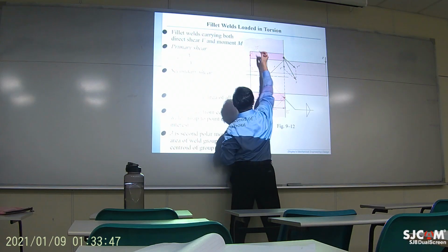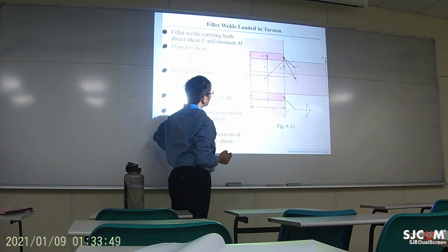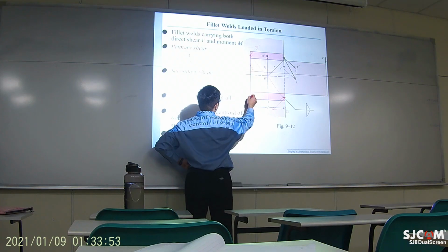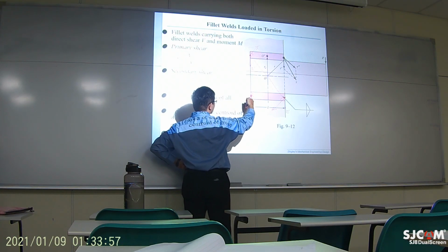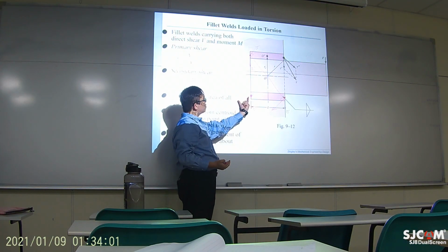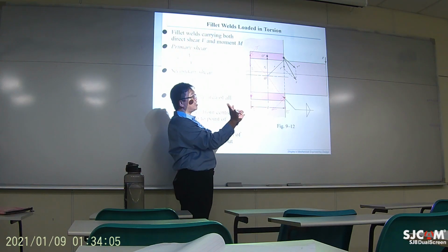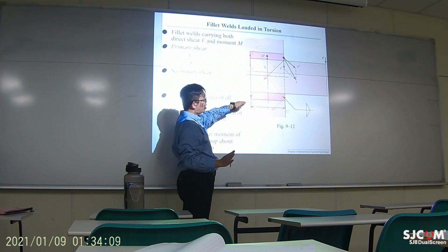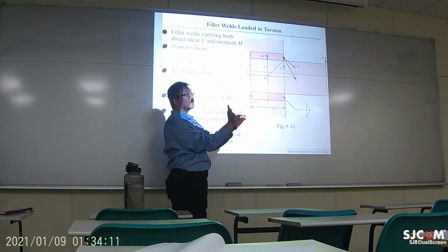So in this particular case, the combination at the left lower corner point ends up with a shorter vector for the total shear, because the spanning angle between both shearing stresses is greater than 90 degrees.